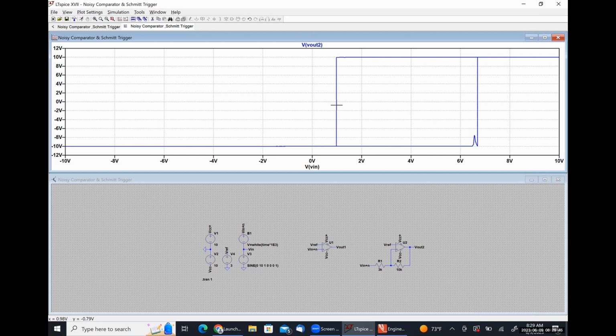The discrepancy here is because we are ignoring any current that can flow through the input resistance of the op amp, okay? So this just gives us a good design approximation. It's not going to be exactly spot on all of the time, but it's going to be pretty close, which is good enough for me when we're trying to design things, okay?